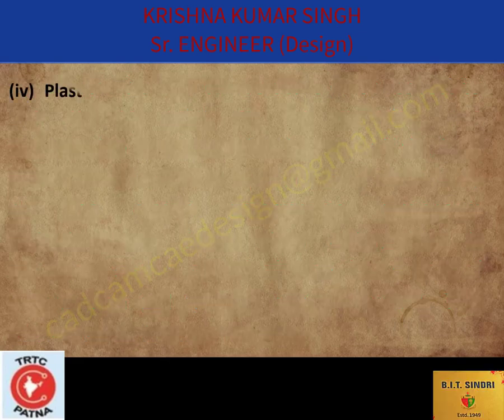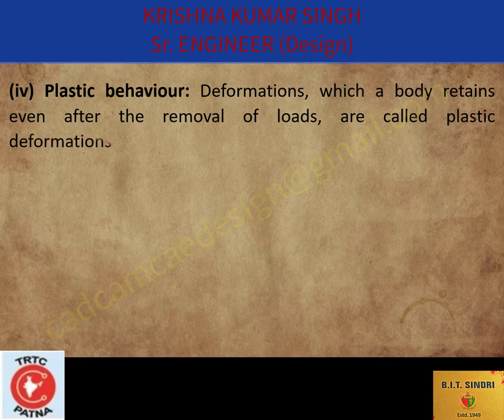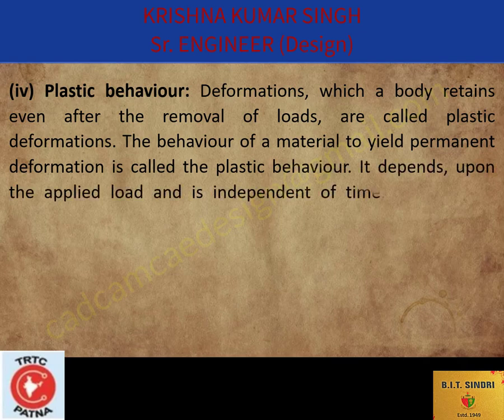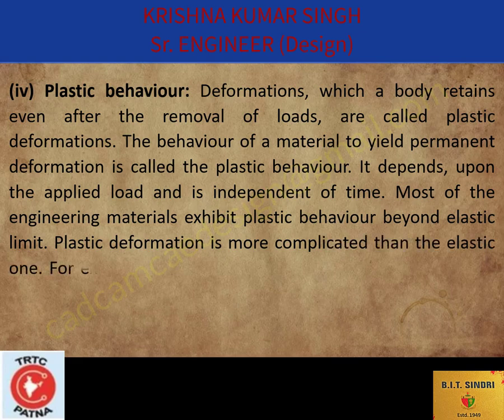Next is plastic behavior. Deformations which a body retains even after the removal of loads are called plastic deformation. The behavior of a material to yield permanent deformation is called plastic behavior. It depends upon the applied load and is independent of time. Most engineering materials exhibit plastic behavior beyond the elastic limit. Plastic deformation is more complicated than the elastic one.